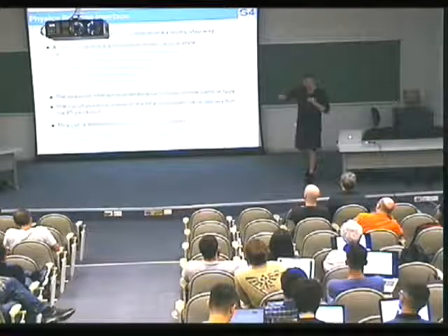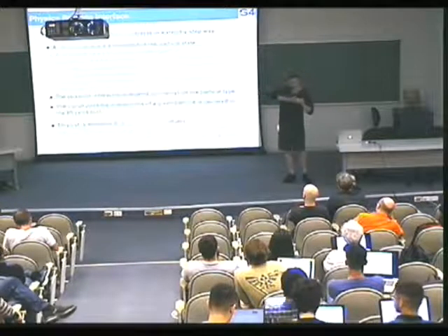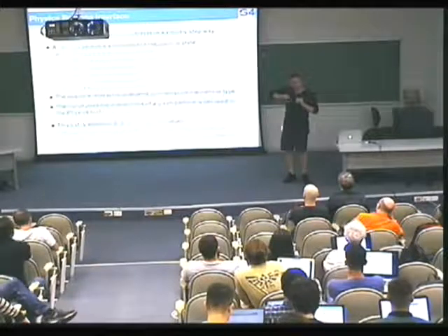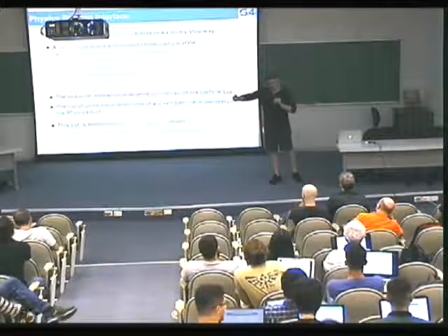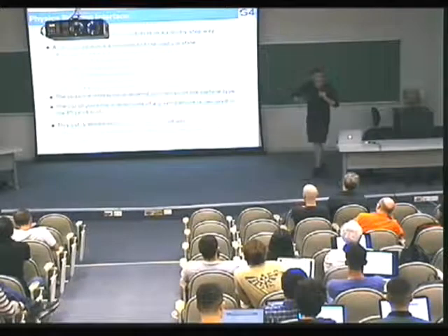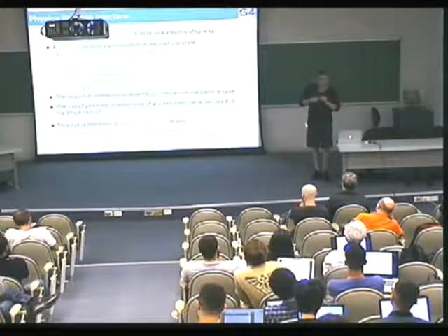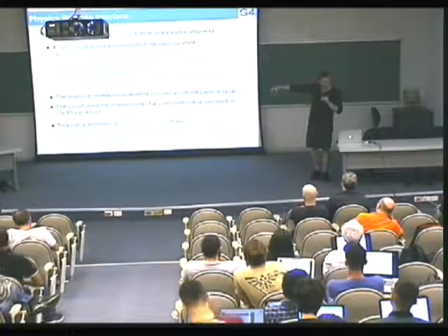Before we go there, just to remind you that Makoto already mentioned that in Geant4, G4Track objects are propagated in a step-by-step way. There is a pre-step point and a post-step point. So something is limiting the step, so we propagate each track from the pre to the post-step point. And we are tracking one track at a time. Okay, we are making one step. If something secondary is produced, we put it into a stack.